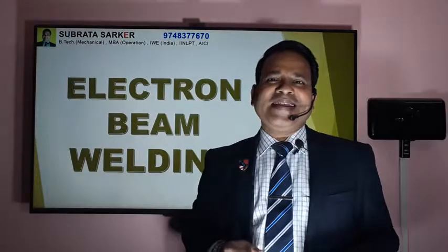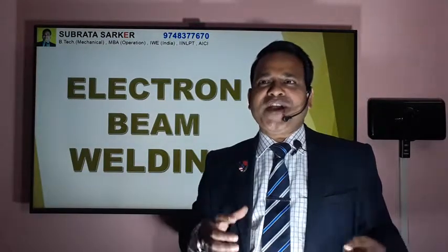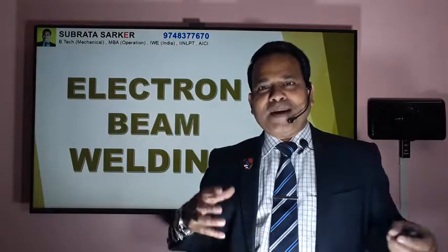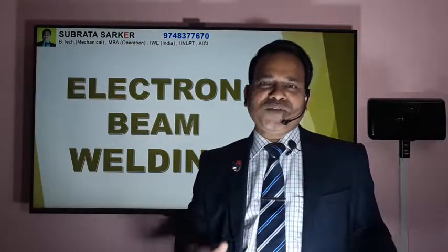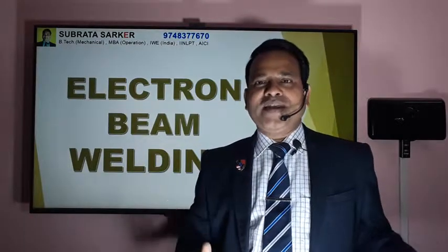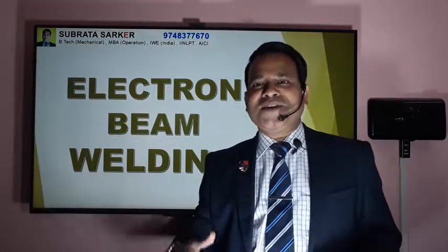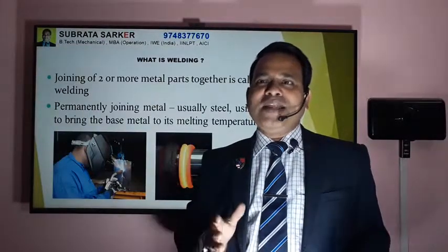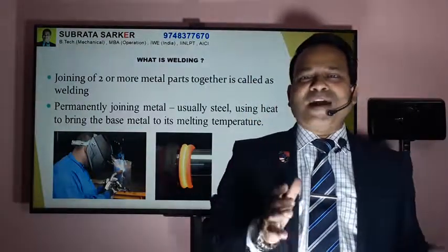Now, what is welding actually? Welding is basically joining two or more metal parts together with the application of heat and pressure both, or addition of another metal called filler metal. So this is basically welding, and welding can be categorized in 5 types.